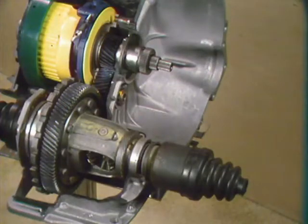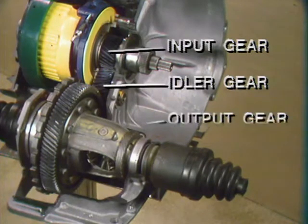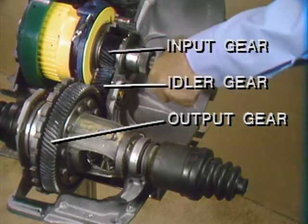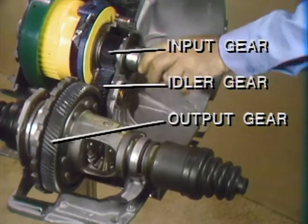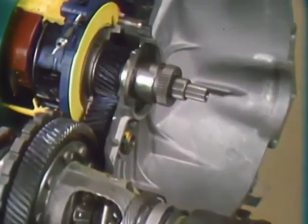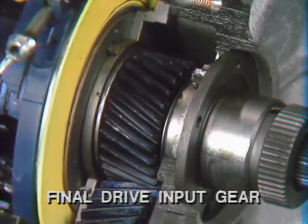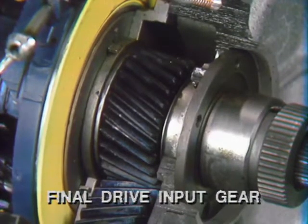From the main planet pinion carrier of the transaxle, power is transmitted through 3 final drive gears to the differential. These 3 gears are called the input gear, the idler gear, and the output gear. They are always in mesh as shown, and are always driven when the transaxle is in gear. The input gear, as mentioned earlier, is splined to the planet carrier and always turns with the carrier.